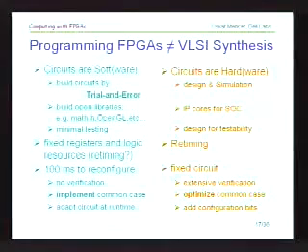The FPGA circuit is a software issue, and you can really ship a product over the internet and then ship a bug fix or ship a patch, just as you do for software. And if you find another bug, you simply fix it by shipping another circuit. So you don't need to go through as rigorous verification and testing as you do on the VLSI side. Programming FPGAs is more similar to actually programming microprocessors, where you write some code, you push a button, you can download it within 100 milliseconds, and you just go through the loop of programming trial and error to figure out what it is that you want to write.